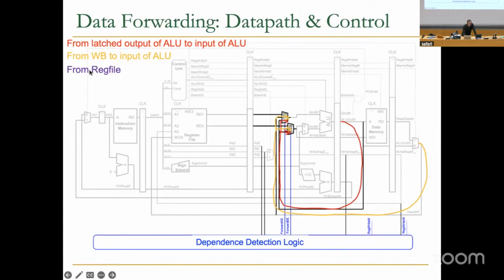And then we also get that from the register file, where we assume there's some internal forwarding, which makes this picture easier, let's say. Assuming that internal forwarding, or a smarter register file, half of the clock cycle you write, half of the clock cycle you read. Okay, so now you can see that this is not that bad, but it increased our complexity.